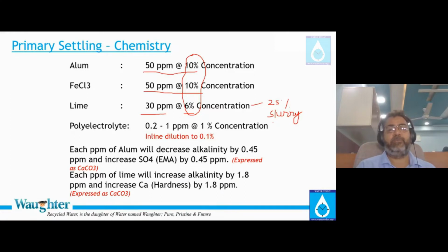And therefore, if you want a proper solution of lime, which is a term called milk of lime, not the sludge, milk of lime. Okay, what is milk of lime? Milk of lime means if you take the lime, mix it into the water, it will appear milky, and after that you allow it to settle. When you allow it to settle, you can go and do this experiment at home, you will find all the white material deposited here, but this liquid is transparent, crystal clear.